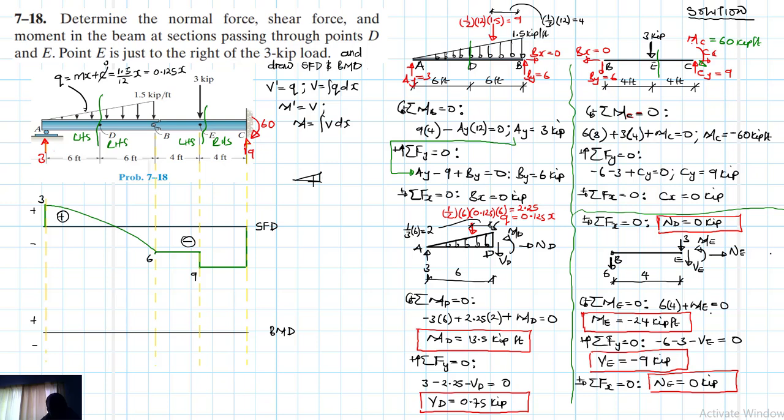You cut this beam, we are just considering this region A to B. You can do this, where you cut the beam, like this point is A, this is our x, if you remember this. Then you will have a V there, you will have moment, and normal force. You can do this and work out, you'll have your equivalent force there, you'll have your q there. You can do this if you want to, then you can find the equations, or you can also just use the differential equations directly. So what I'm going to do is use the differential equations directly, and we'll find moment at B, which we expect to be equal to 0.